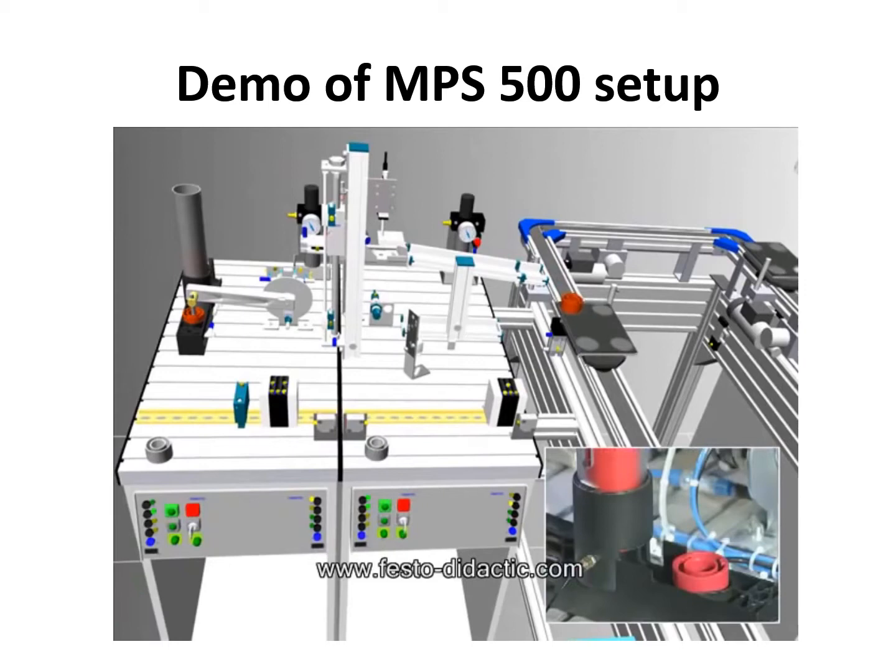Operator could stop the system by pressing the stop button, or could start the system by pressing the start button, or start and reset LEDs could be used in the PLC programming to indicate some signs. For example, the system is ready to be started when it's blinking. Okay, so then the operator knows that this is time to start the system. Or there is an error and the reset LED starts blinking, yes? So then the operator knows that something is wrong in the system and should stop the system.